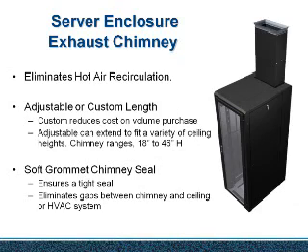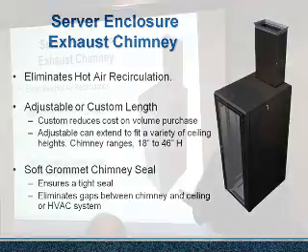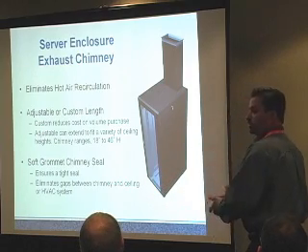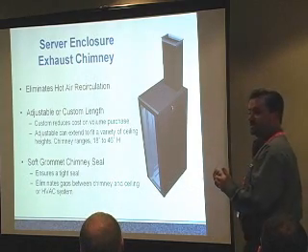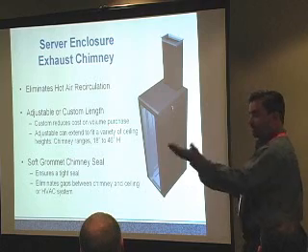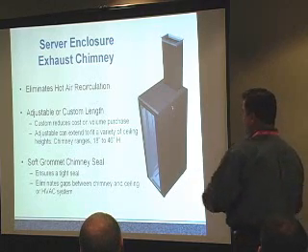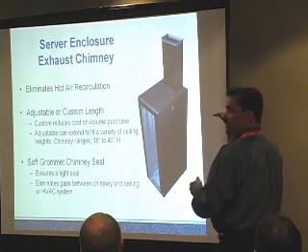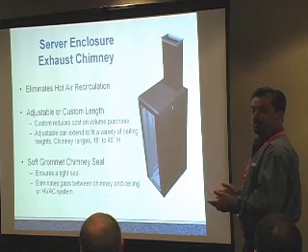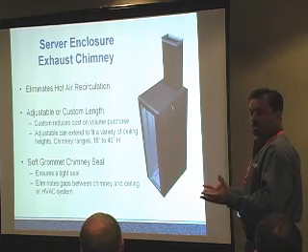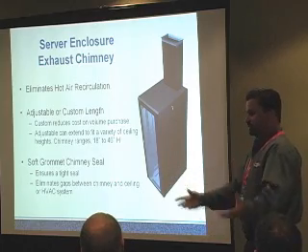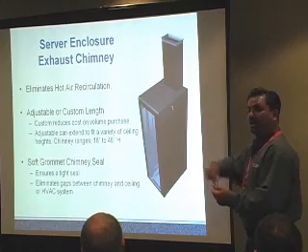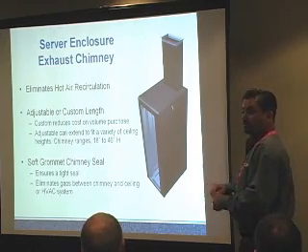So inside the enclosure as well, now you have to manage the hot air. How does that get out? Via either a split mesh door or a split fan door, assisting just the front cold front-to-back draw going into the hot aisle, or using a solid door and ducting the hot air right into your return plenum. Therefore, you have no recirculation in the data center at all. So the whole data center has no heat generation in the room. It doesn't recirculate. The brushed grommet kit inside the enclosure keeps that from recirculating back to the front air intake as well.